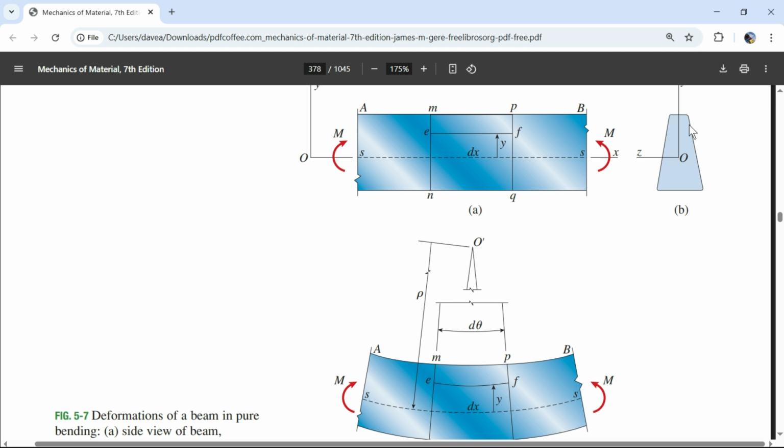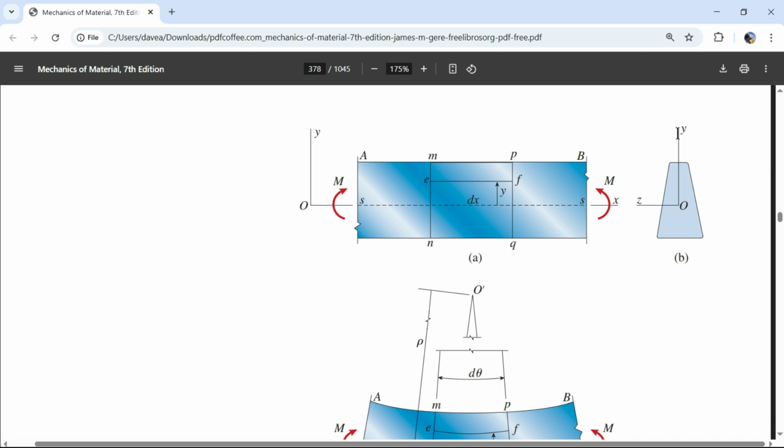Well, then that volume is increasing that way, in the z direction. And if I pulled up and then down, that little volume is increasing that way. So that's what's happening in the y and z direction, and those are what we consider normal strains. There's no angle that forms, the little cube doesn't turn into a diamond shape.